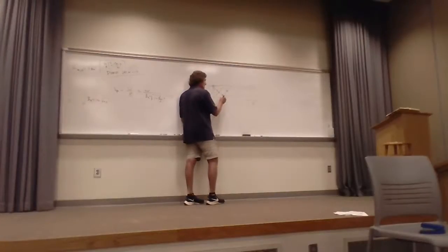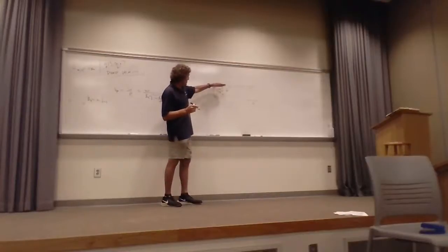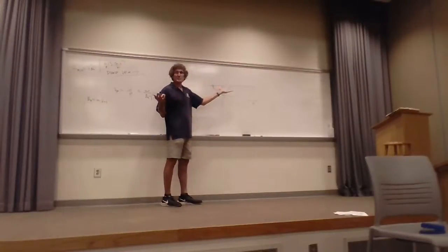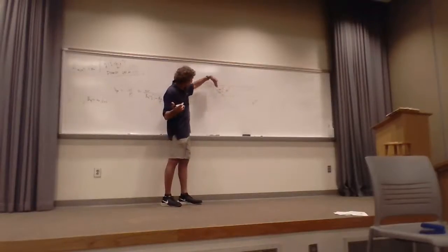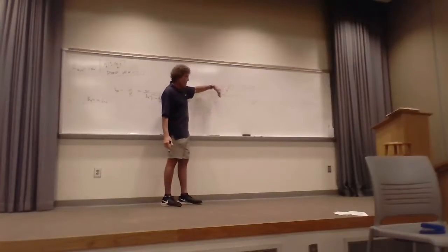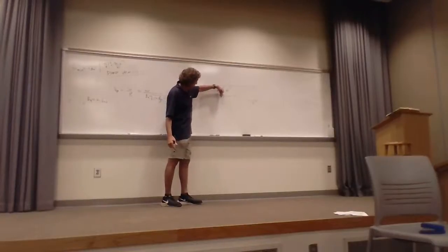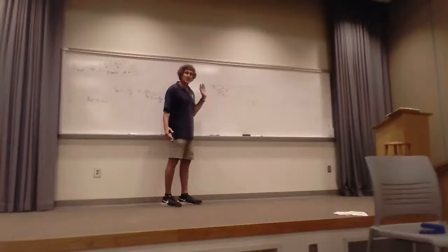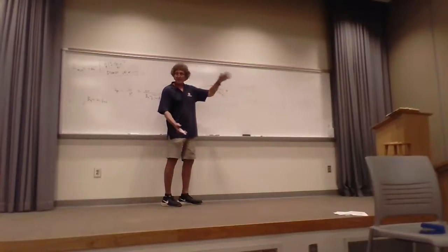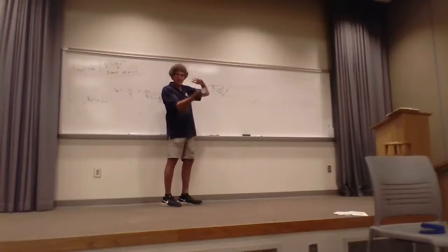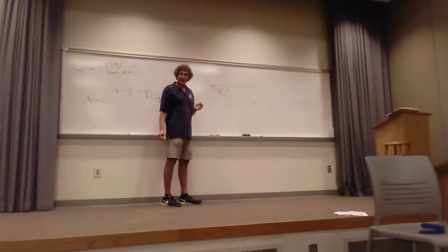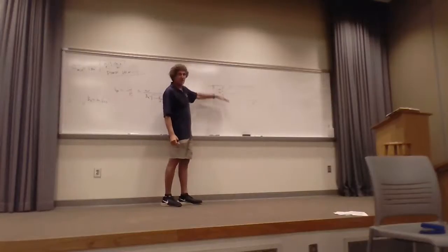They're basically going at some angle of incidence. And I guess what I can do is show you this, some angle of incidence. Now, as that angle approaches 90 degrees, as the thing's moving down, it's moving at the speed of light in that material. But when the wave's just bouncing like this and that angle's getting smaller and smaller, when it's bouncing just straight up and back, there's no net progression of the wave down the guide. The wave is just bouncing up and down like capacitor plates or something like that. And that's when you're at cutoff. All the energy just bounces up and down, nothing propagates.